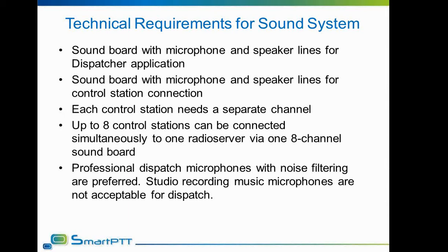SmartPTT supports independent access for left and right channels of a stereo device. That gives the ability to connect two control stations to a PC even with a standard stereo microphone input and speakers output. Also, it means that any stereo input-output on any sound card could be used for two control stations. SmartPTT supports ASIO drivers for sound cards as well.